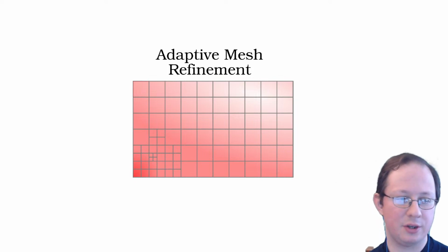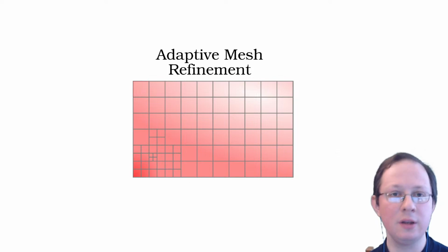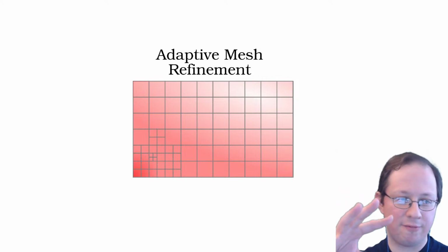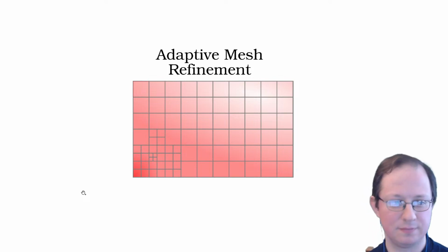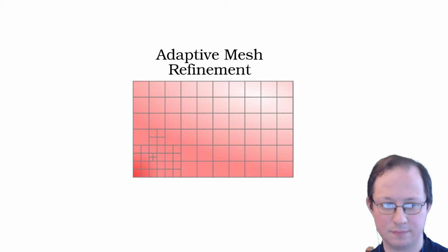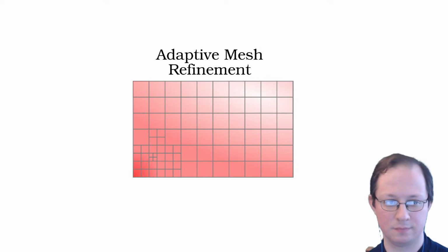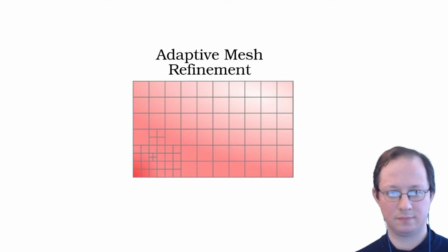So you would need some sort of octree type deal, right? That you would need to have. Yes, exactly. The difficulty is that currently, without mesh refinement, you can do direct grid cell addressing. The grid cells are all stored in a 1D array, and based on the X, Y, and Z size of the cuboid box, from the thread index alone you can tell at which coordinate you are in 3D on the grid.